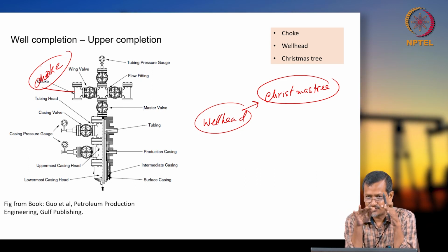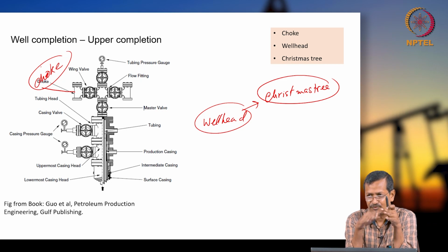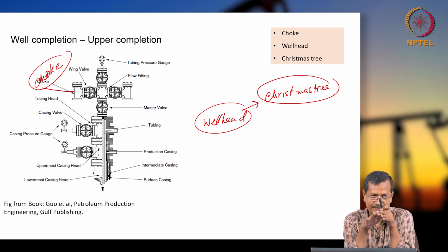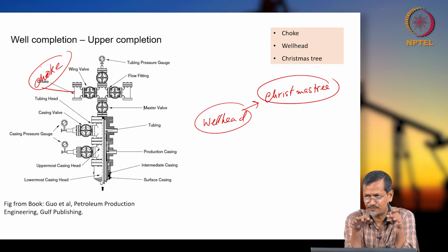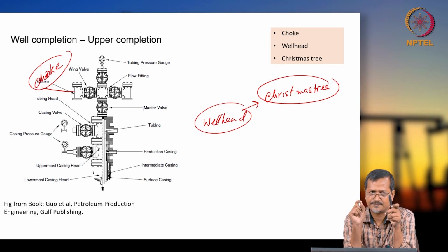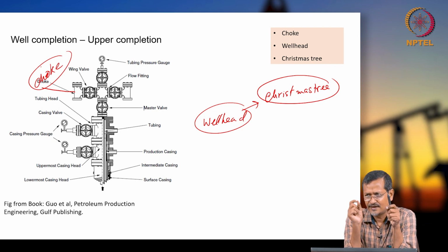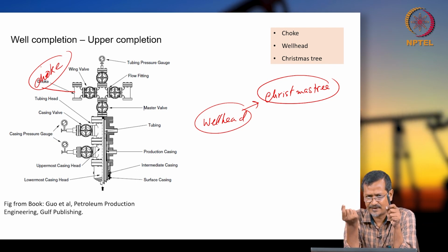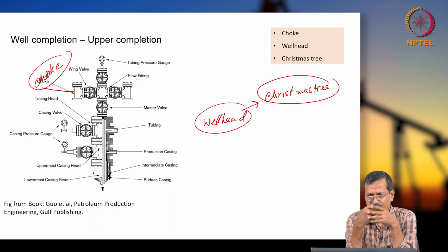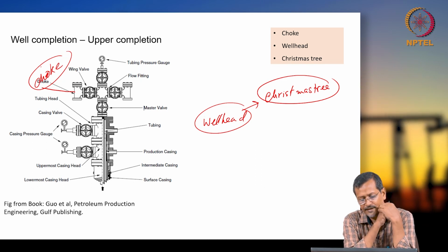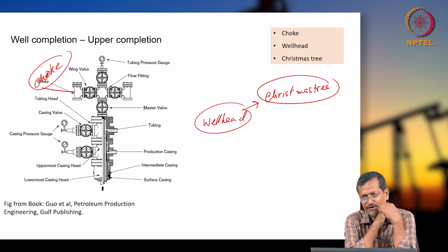So sand, you try to minimize, you cannot stop 100%. If you stop 100% of sand production from the wellbore, that means you have to stop the whole production. So there will be some sand particles with very fine diameter, very low diameter, that will come with the liquid oil or water. And if you have corrosive gas, many times you cannot avoid it, you have to accept it.